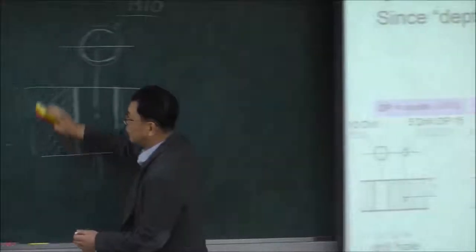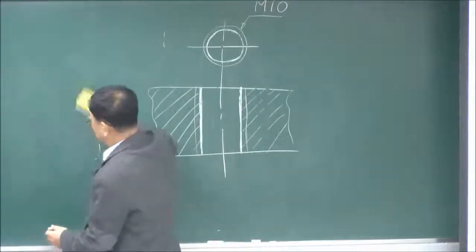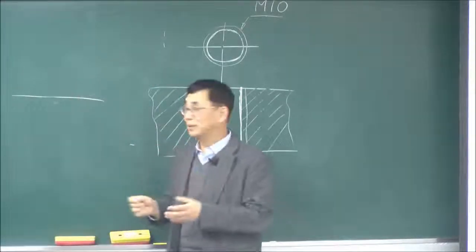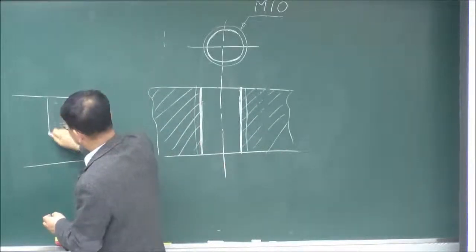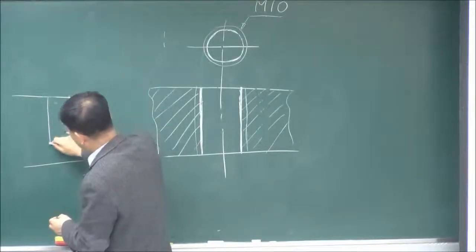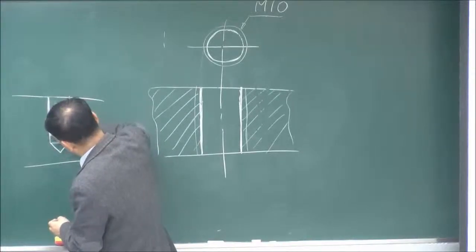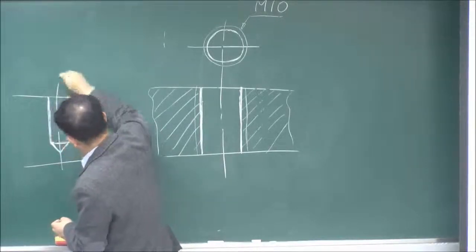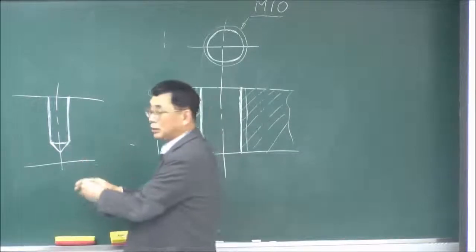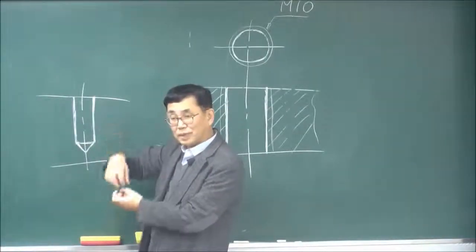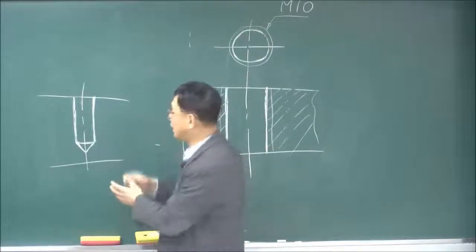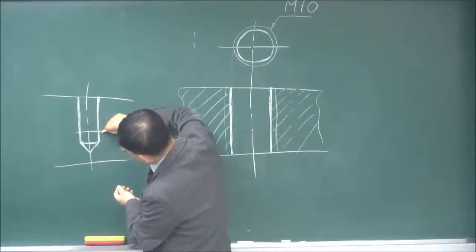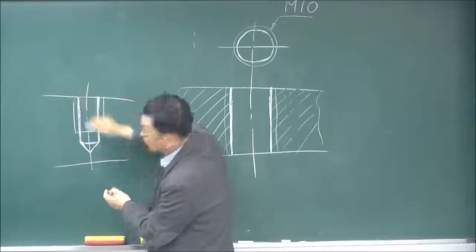In the slide, you may see that if the tapping hole has some depth, then firstly the drill hole is drawn. The first step is to make a drill hole, and then using the tapping tool, you make a thread until your desired depth.